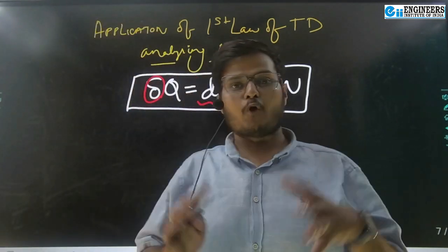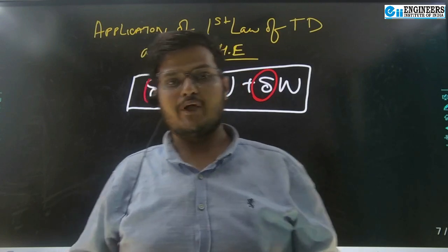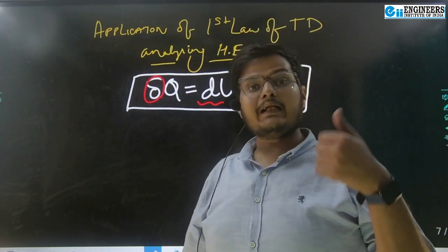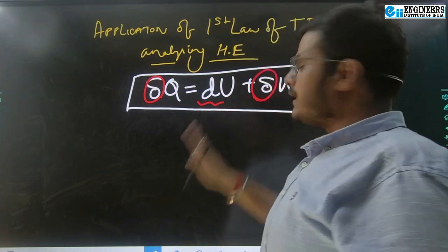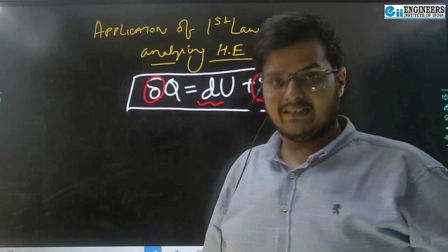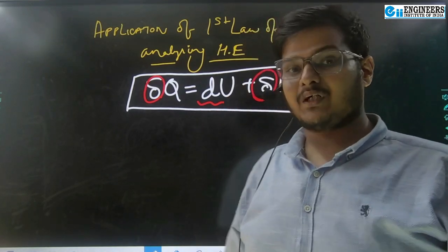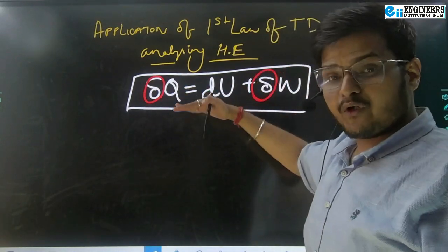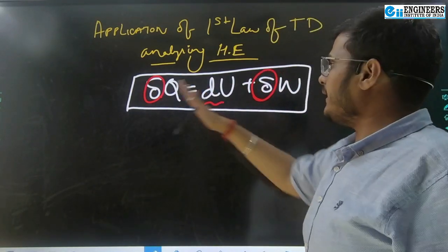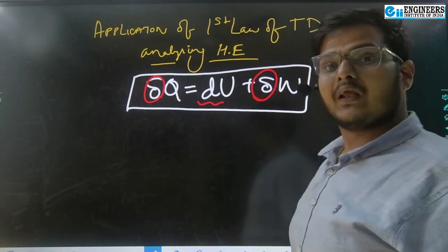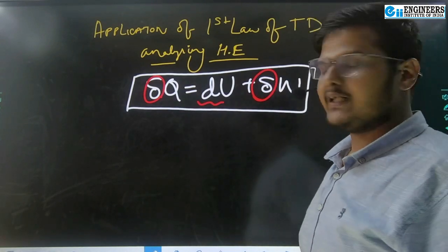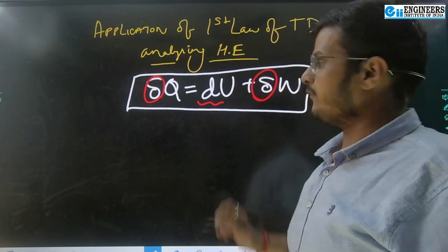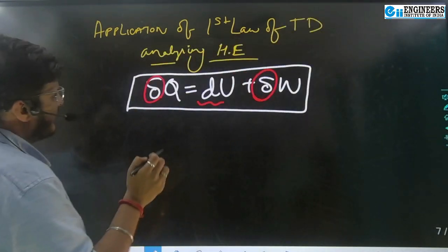Here comes the property aspect that we studied in thermodynamics. Heat and work are path functions. They are indefinite integrals. Internal energy is a point function. It's a definite integral. It's the property of a system. That's why work and heat are always designated in terms of δ, because of the indefinite integral condition, and dU is because of its finite differentiation or definite integration.